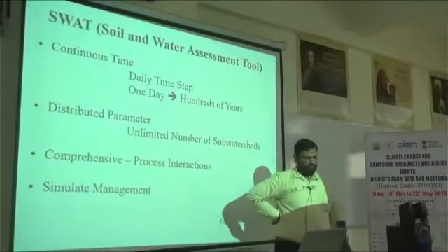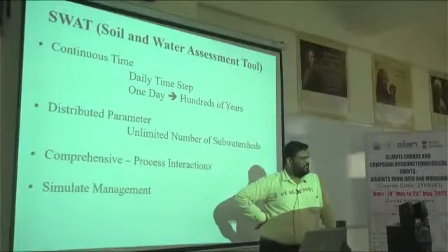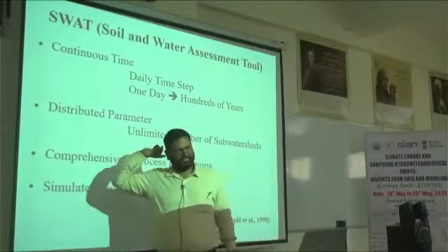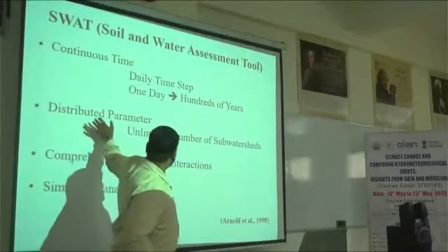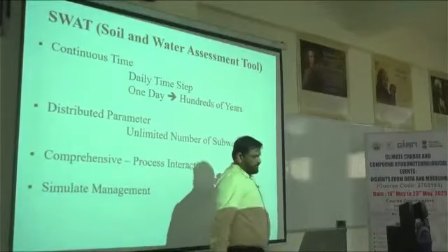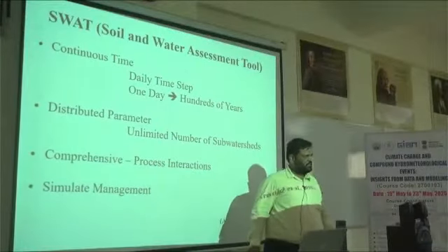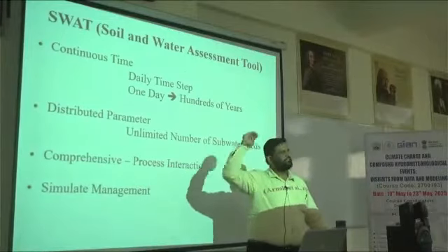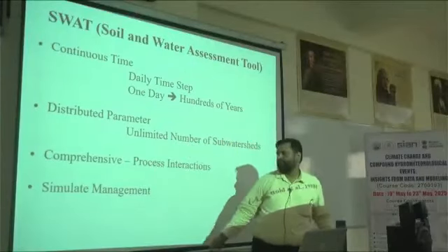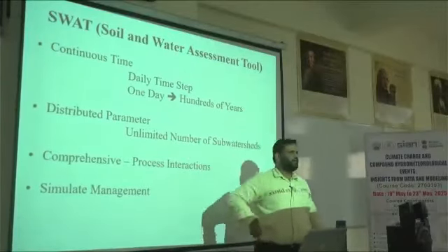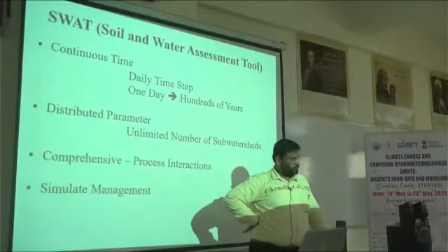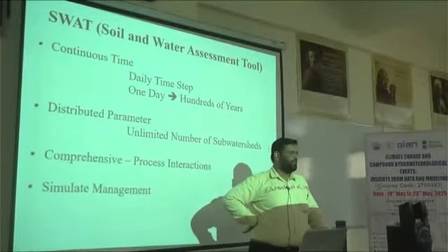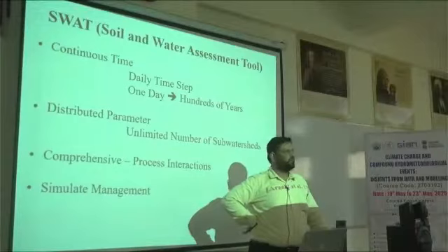Now come to the SWAT model. Basically, the SWAT model is a continuous model, physically based, semi-distributed. By mistake I have written distributed, it is semi-distributed. Okay, then a process based model, physically based model, that simulates the management practices, as I said. Why is SWAT different from any other hydrological model? Because it simulates the management practices also, provided you have the knowledge of where and how to give those management practices in the particular SWAT model.